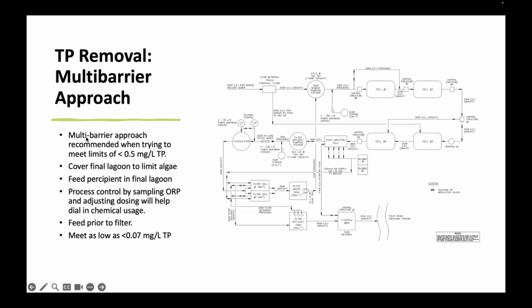And so they're actually targeting here a 0.07 phosphorus, which seems crazy to me. I mean, it's not crazy. It's going to be done. But from a low phosphorus standpoint, if you'd told me we could do that 10 years ago, I wouldn't have thought so. But we've made so many advances in filter materials and the way we approach this that now we can.